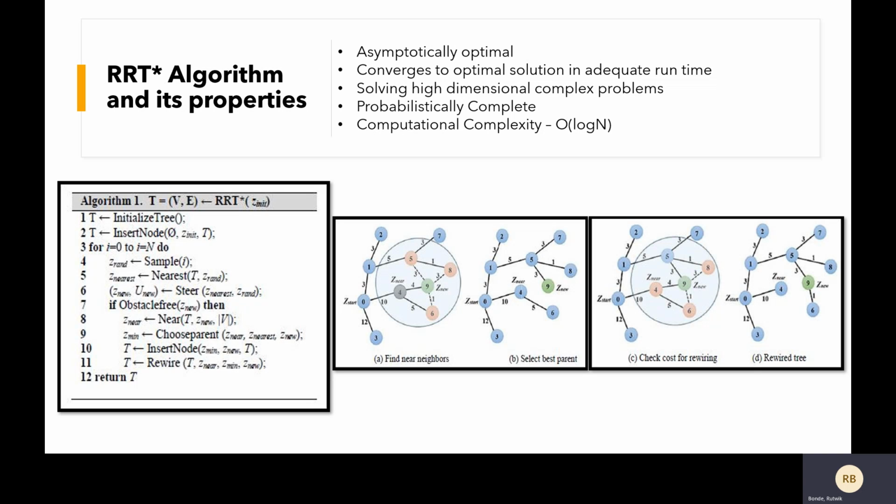If the random point lies in free space and is also accessible to the nearest neighbor according to a predefined step size, then a local planner inserts it in the tree by connecting the random point and the nearest neighbor. Otherwise, the planner returns a new node by using a steering function and adds it in the tree by connecting it with the nearest neighbor. This property of RRT to explore regions in free space is called Voronoi bias.